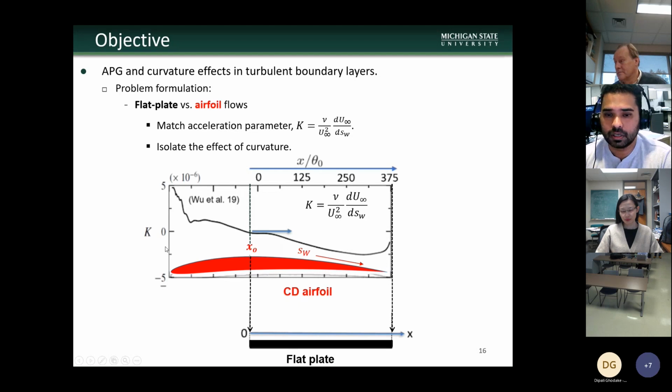So we wanted to skip the laminar boundary layer, laminar-turbulent transition, and FPG effects, and focus mostly on fully developed turbulent boundary layer with adverse pressure gradient effects, right? So we started our flat plate simulation at the midchord location of the airfoil. Starting from midchord towards the trailing edge, we match the pressure gradient along the streamwise direction along the chord of the blade on a flat plate.